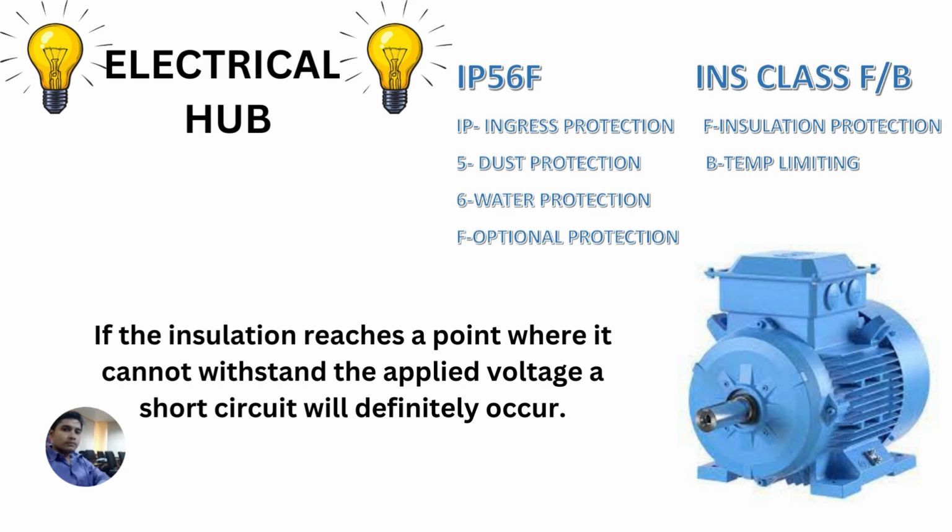So, for example, the mentioned temperature of operation is 90 degrees. Now we assume that the life of the motor is 10,000 hours. What will happen? If the motor operates at 100 degrees, the life of the motor will be 5,000 hours.